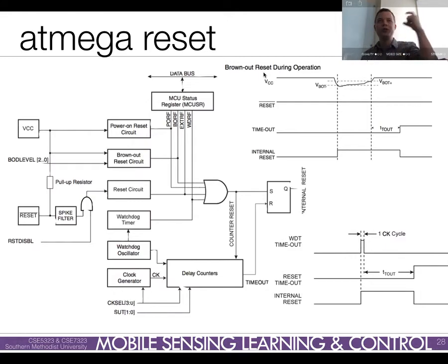And so when the voltage on the battery gets right on that threshold, the microcontroller starts just turning on and off. It just starts going nuts. It goes crazy, right? It can rewrite itself. It can undo code that's there. All sorts of bad things can happen when that happens. So there's this thing called the brownout reset, which looks at that voltage. And if that voltage ever drops below a certain value, it's going to shut down the chip. And it is not going to turn that chip back on until it gets to a higher voltage value than when it browned out.